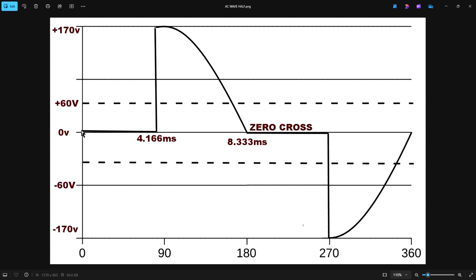When you wanted it off, you would turn the voltage off to the gate, and at the very next zero cross, it would stop conducting and your light would go out. It's basically a switch, a relay. Think of it as a relay, but it's a relay for AC. And that's what it's used for. All these little solid state relays you see that you can buy online, that's how they work. There's some extra components we'll talk about in them, but this diagram's here for a reason.